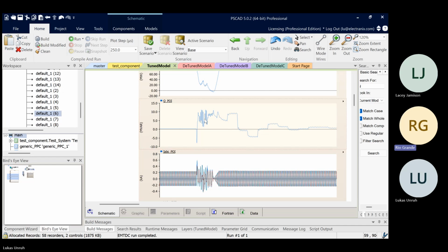And you could probably argue that it doesn't meet the 2100 requirement for fault current that I mentioned before. And in terms of the settling time and the settling band and the response time, that's probably a valid reason to get this behavior corrected as well. But yeah, I would probably make a note of it and look at it in a system study if you're planning on doing one. If you're not doing a system study and this is your only opportunity to look at it, then I would probably get it fixed if you can.